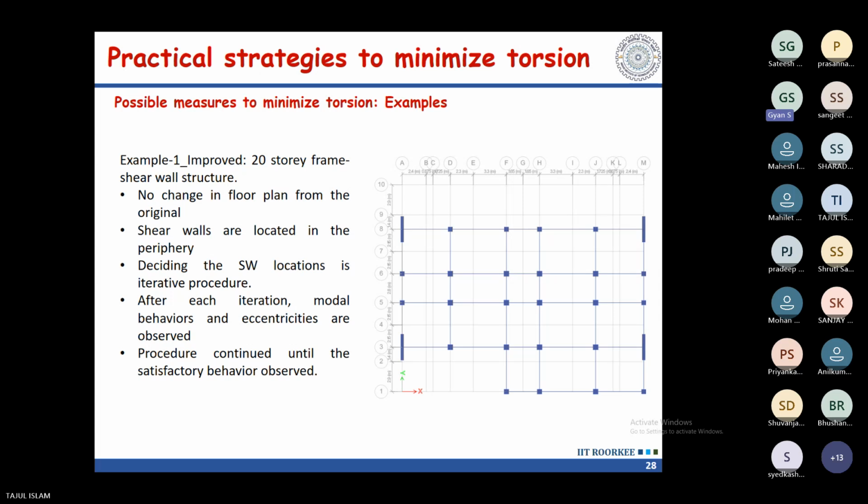Yes, spandrel is a horizontal member, a deep member. It will always help resist the lateral force also. But I can make it a bending behavior by dividing into a number of segments. If suppose 10 meter is there, I can divide it every 1 meter. I can assign one single pier AD, single spandrel AD. Then the bending moment will come like your normal beam.